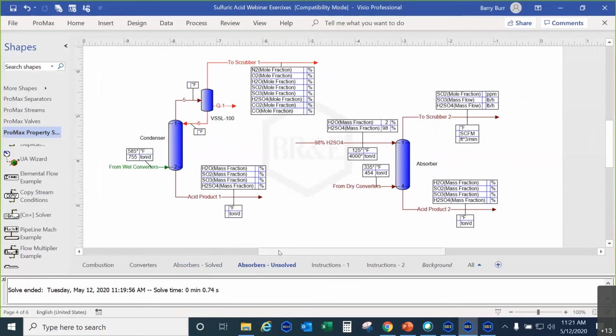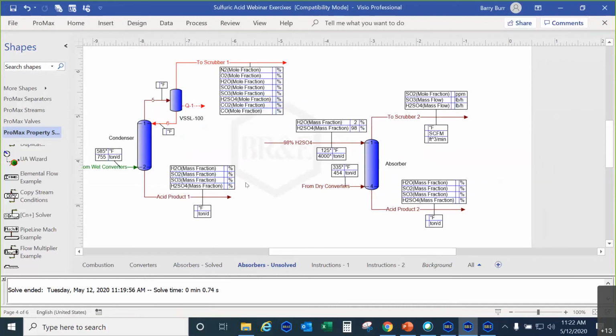That environment with the NRTL is not selected, and it doesn't have the reaction for the SO3 absorption added to it. So we've got to create that reaction. We've got to create that special property package, and then we're going to specify the blocks here so that we get proper SO3 absorption in these distillation columns. So there'll be reactive distillation columns when we're done.